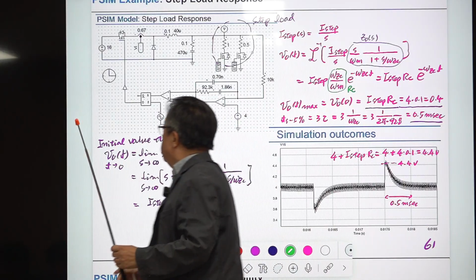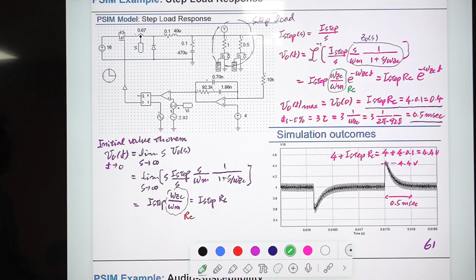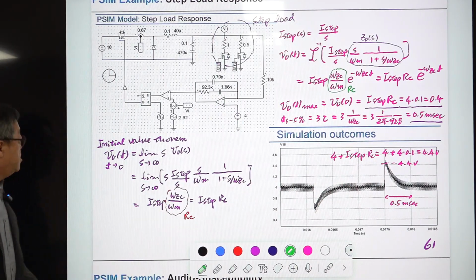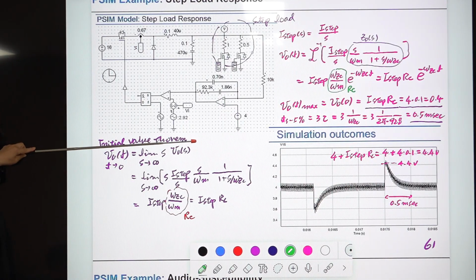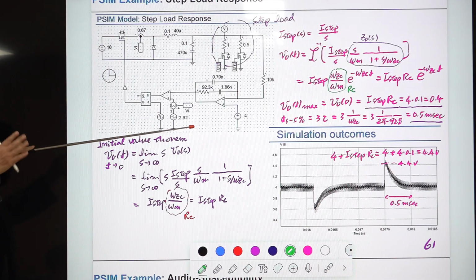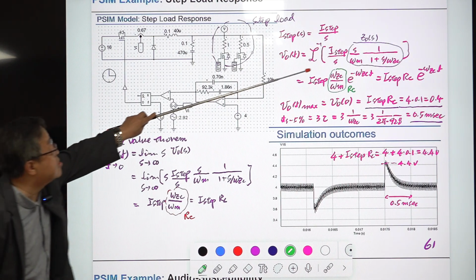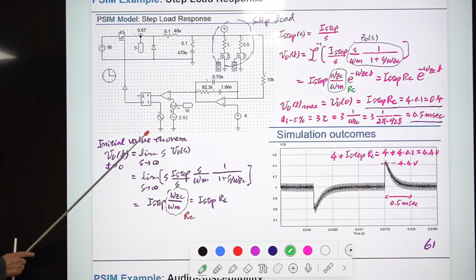Okay, this is some digression. Think about this initial value of jump. That's called the initial jump. You know the initial value theorem is coming from the Laplace transformation. You have the table of the formula. Then this initial value is the S domain expression of output voltage, not output impedance. This entire one, you multiply S in front and send S to infinity. That is this value, T goes to 0. That is the initial value.